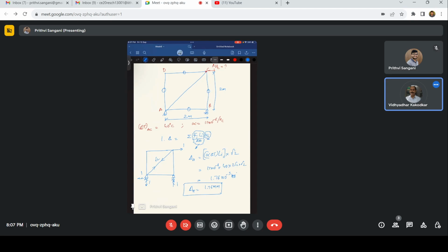This is too short. So right now we don't simply fabricate somewhere here, because the gusset plate or whatever joining plates are available are located at that distance only, right? Two and two at those grid locations. So we need to pull it. Usually we'll be pulling it and then fixing it.